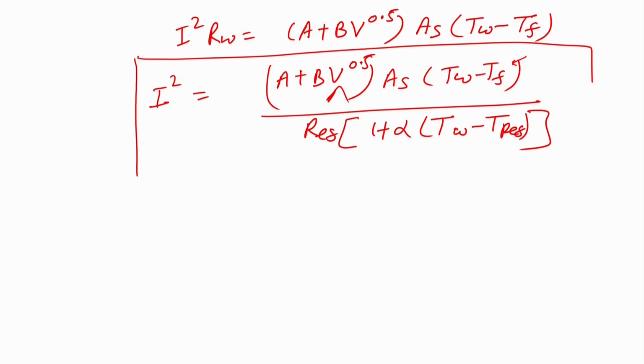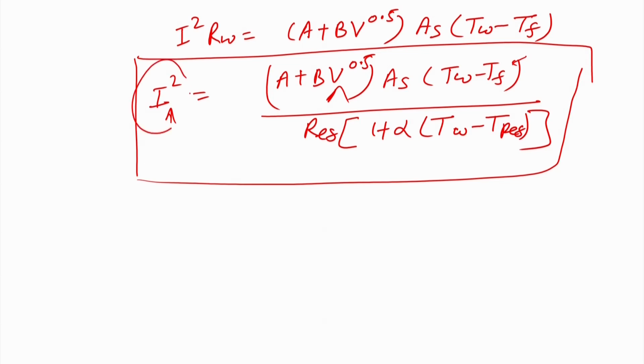So, if you know your reference temperature, and you know how much the temperature has changed, you can calculate the velocity. So, what do you need? You need the fluid temperature, and you need I square. If you know that, you can calculate this value. If you do not know that, what can you do? You can convert it in terms of constant temperature. If you maintain the temperature constant, you can find how much current value needs to be accounted. So, either you can keep this I square constant, or you can keep this temperature difference constant.